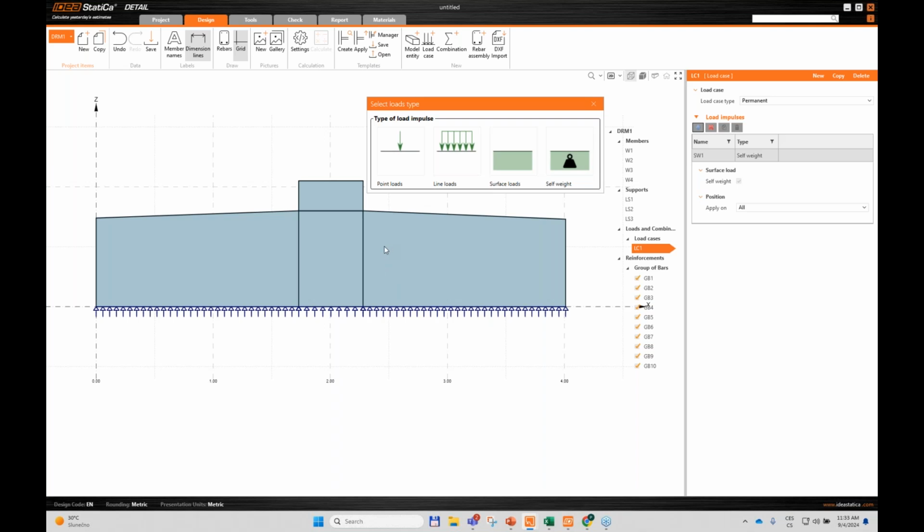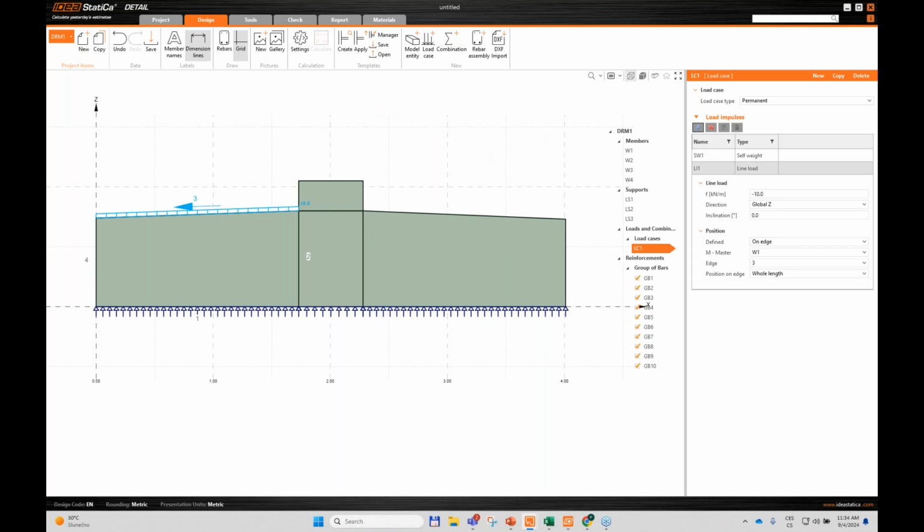It can be good to know if you often model just part of the structures as the frame corners and so on. So you usually have probably the global model from the 1D elements, and you are able to get from that model the internal forces like a normal force, shear force, and the moment. And you can easily recalculate these forces for the length and input it as the line load, and that's what I will do.